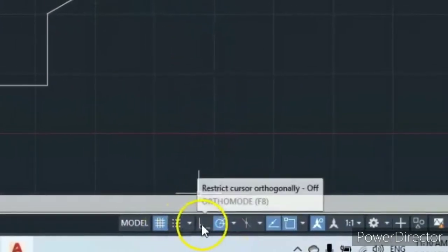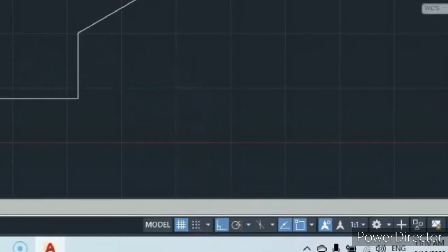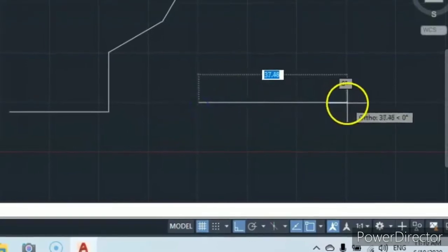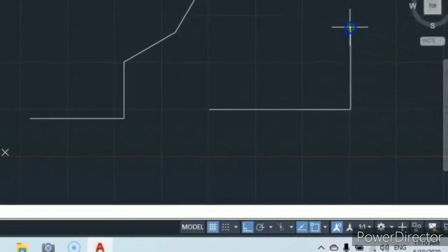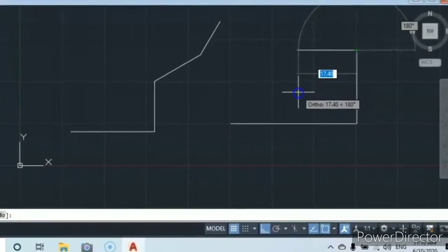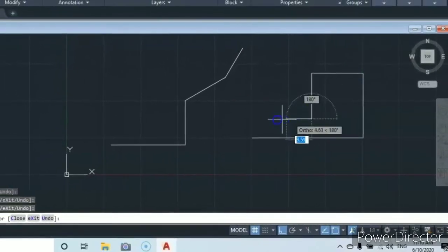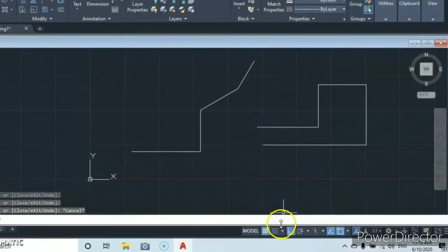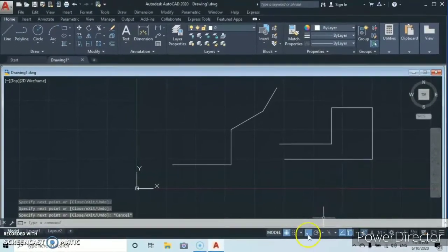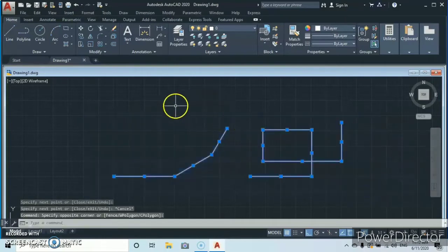And when you activate angle 90 here, and then you go to the line command, you can only draw vertical or horizontal lines. You can go like this, then maybe come down here like this. No matter where you move your cursor, it will either draw horizontal or vertical, because you activated angle 90. So you see that we cannot make any other angle because we activated it. So we escape, and then let's cancel this out. So that's all about making angles.